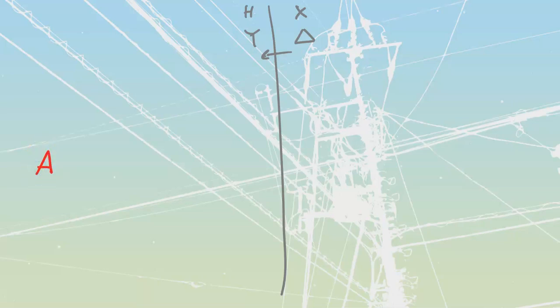Drop in that A, make those two lines, the 30-degree line to where the neutral needs to be, the 60-degree line to where the B phase needs to go and be. And once you got those two in, we can erase those two lines. Once we know where A and B are, we can create C. And now we're just going to play connect the dots going over, and we're going to place H1s on each of these lines.